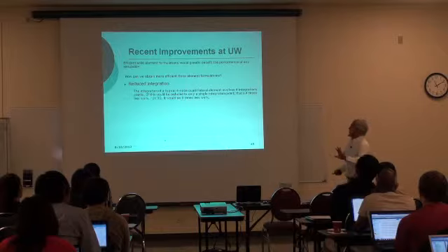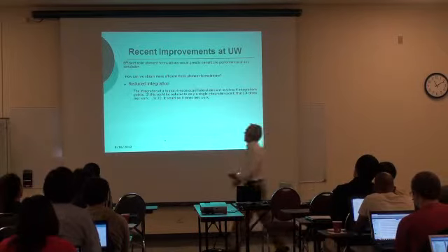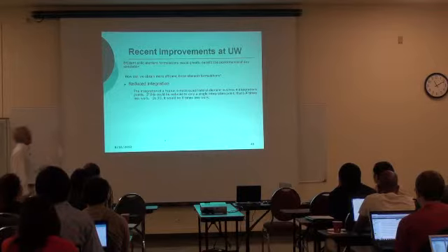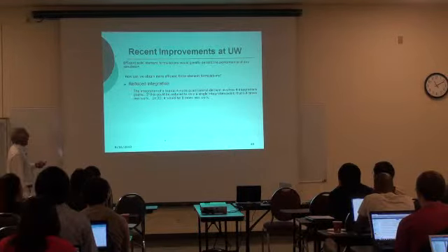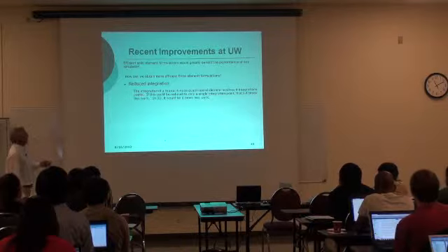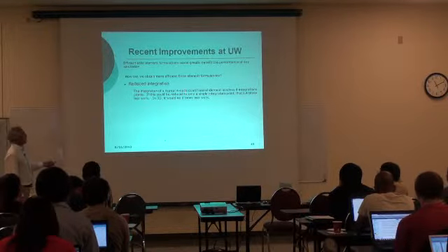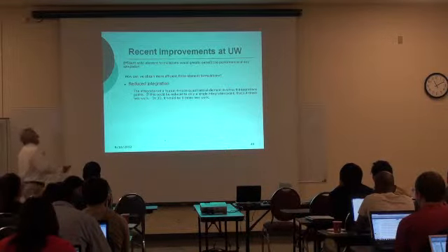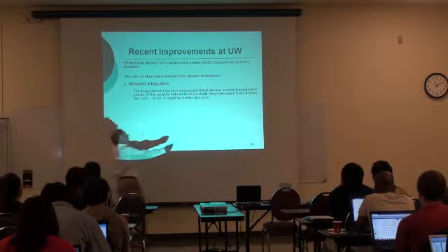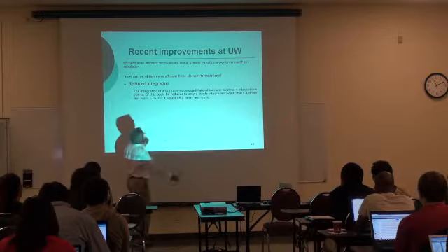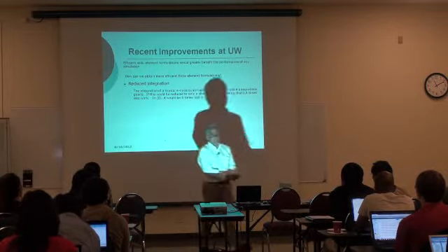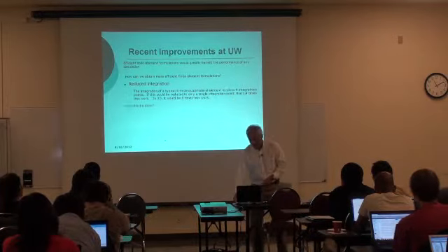I just want to mention this idea of the stabilized single point elements. As I mentioned, the integration of a typical 4-node quadrilateral element involves 4 integration points. If this could be reduced to only one single integration point, then you are doing 4 times less of the work, or 8 times less the work in a 3-dimensional case.